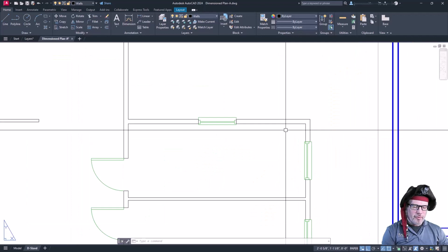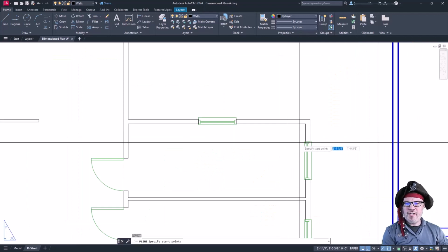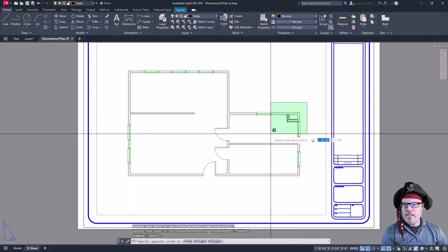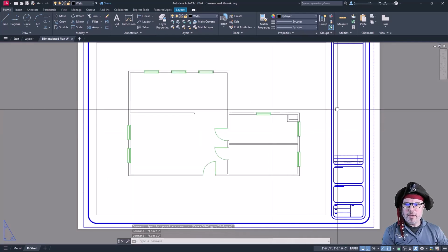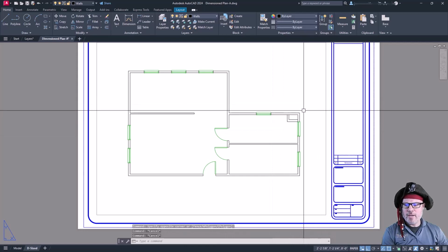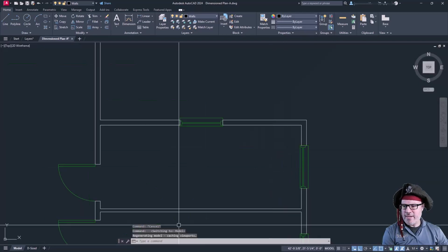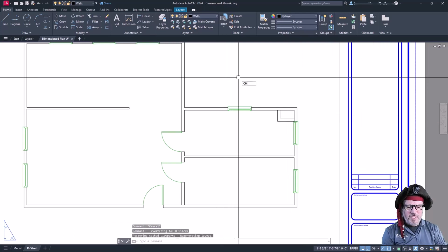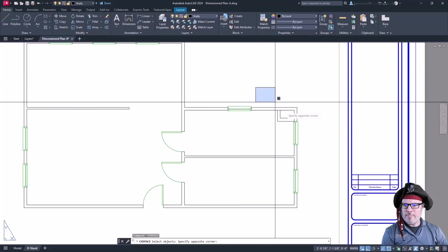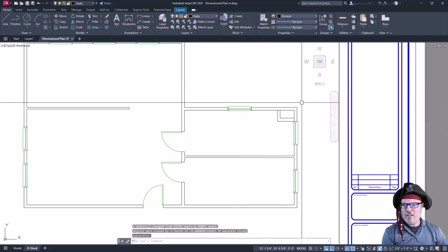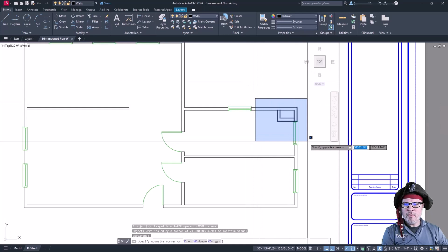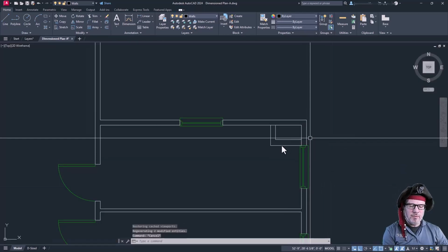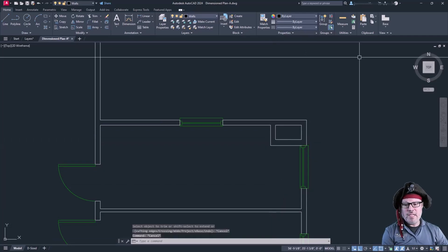If you've ever been working through a viewport on a sheet and you start drawing content, and then realize that content was accidentally created in the paper space layout instead of in the model space, so that it doesn't show up in the model area, you don't have to fret anymore. All you have to do is type CHSPACE, select the object that you want to move, hit enter, and it automatically pushes it through the viewport window into the model space area at the correct scale and size, so that you don't have to redraw it any longer, which has saved me many times.